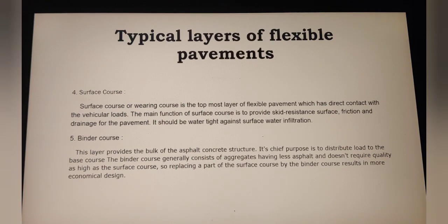This is in direct contact with the vehicular surface. Its function is to provide a smooth, strong, abrasion resistant and reasonably impervious course, because it is in direct contact with the tire. It has to resist the imposed wheel load and transmit them directly to the lower layers.